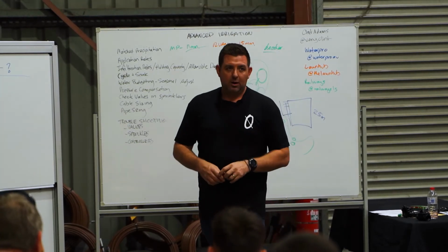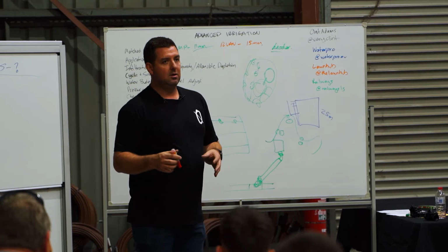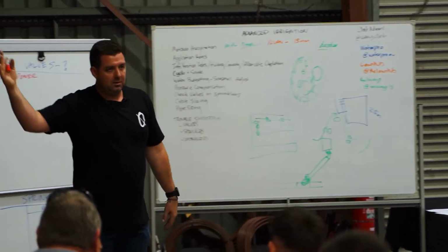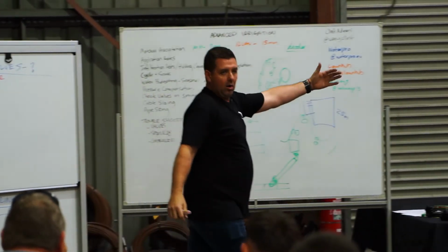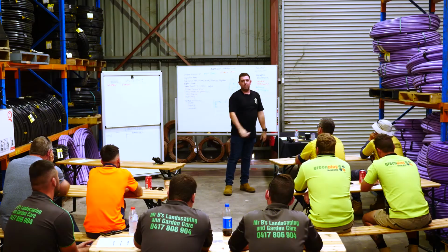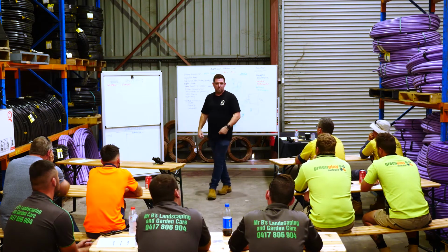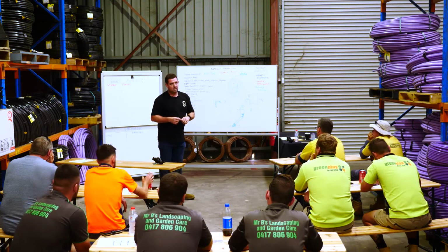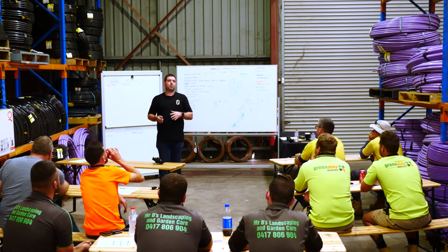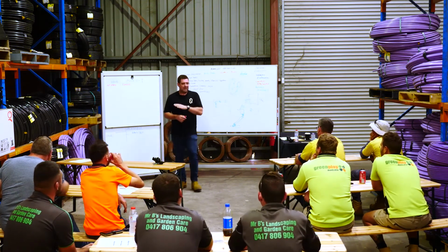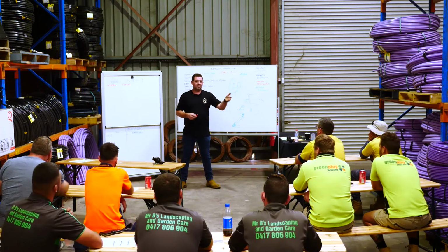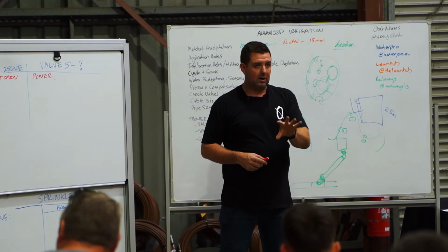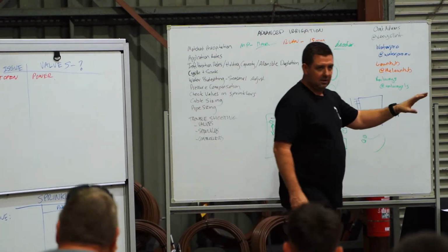If you have that situation, it's going to be really hard for you to find it, because all you know is that at the controller, there's power, and at the valve, there's not. And there's 20 meters of cable and concrete and lawn to work through. If you get into that situation, this is probably the most important thing. When we're troubleshooting anything, you want to go with the easiest, most common, least amount of digging and cutting work to try and work out what's going on before you start digging things up and cutting coils off.